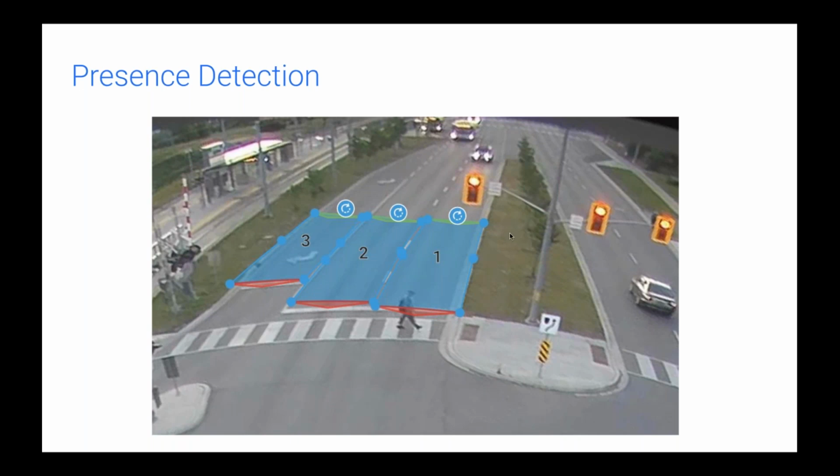So in this scenario, we've set up lane by lane detectors. So it looks like the 2 through movements are their own detection zones. And it looks like we actually have what is probably a protected right turn here. So that has its own detection zone, and that's going to be tied to its own phase within the controller.